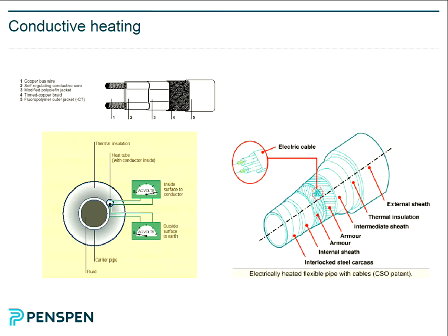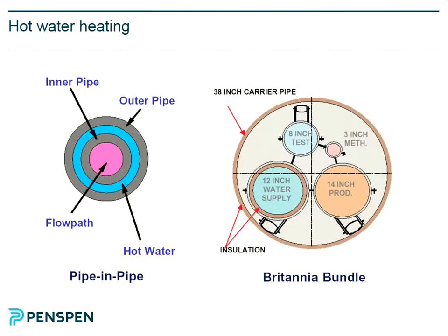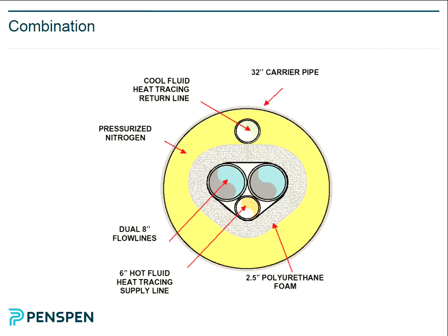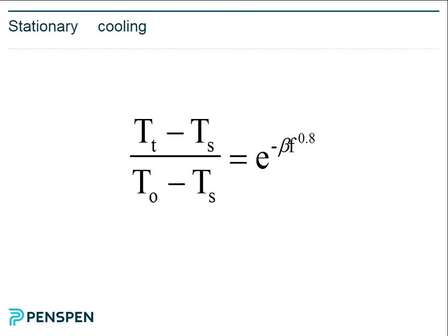So this is an example of a buried pipe under a steady operation, under a temperature profile. So this is the big scale. That's the seabed. This is the pipe under the seabed. This is the bigger scale. That's the sea surface here. This is the pipe. The red is 70 degrees. The light blue is 11 degrees. This is equivalent to the sea temperature, which is 4 degrees basically. So 70, 11, 4. So this is the operating condition.